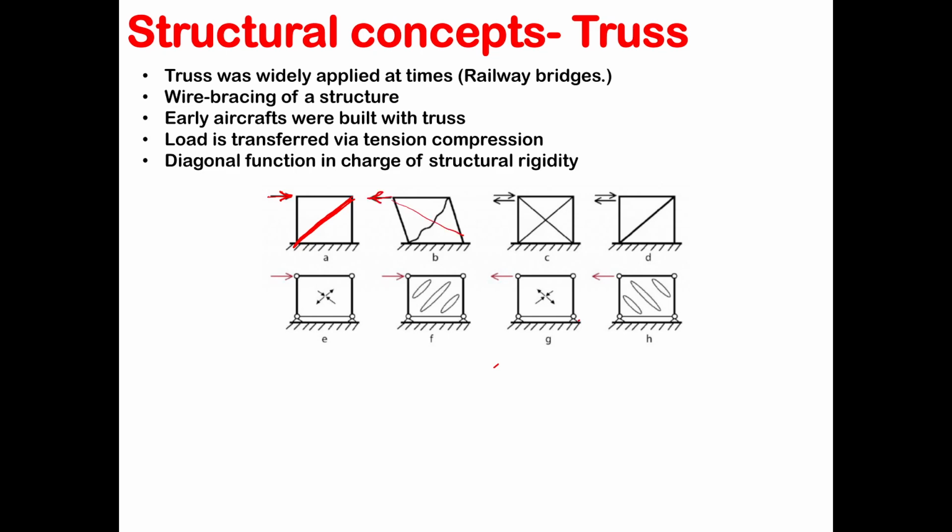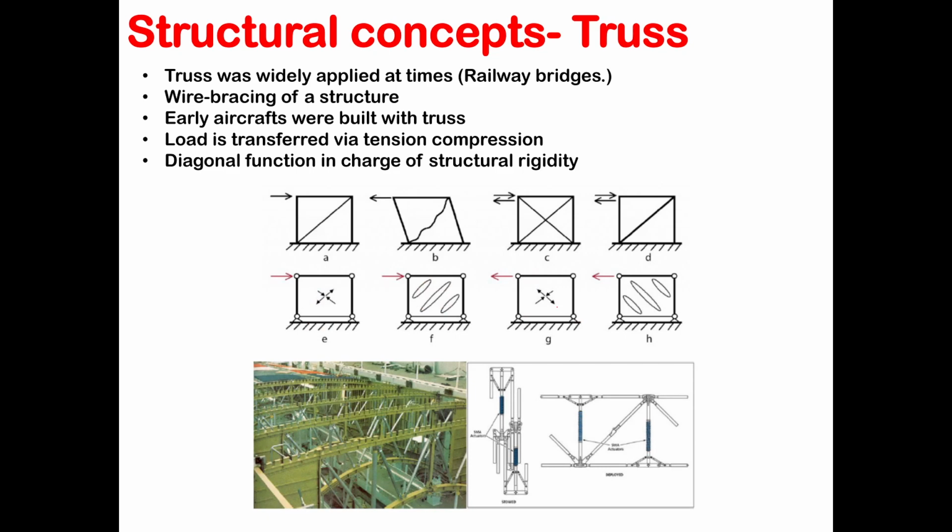These are actually shear forces. So truss cannot withstand any sort of shear force. So that's the problem with truss. That's why we end up adding plates in the truss structure. But examples of the truss structures that are still being used in the aircraft industry can be seen here.